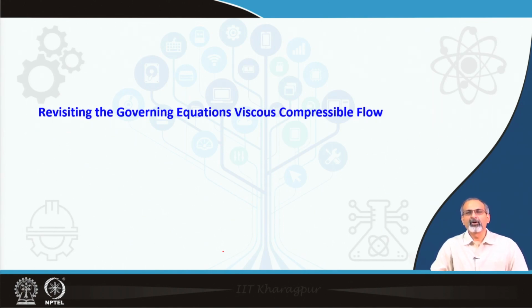But remember that all these approaches are not really applicable to complicated vehicle geometries, where not all of the flow happening on such a complicated surface can be categorized as a boundary layer flow, or we cannot even say that when the flow complicates because of its geometry, these nice engineering correlations are going to give us reliable results.